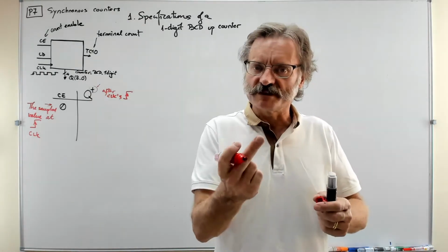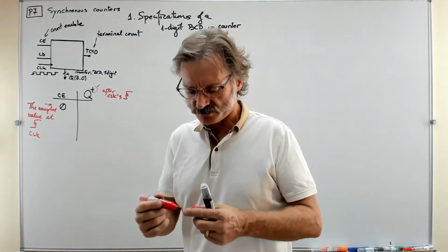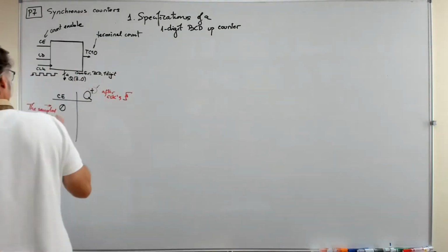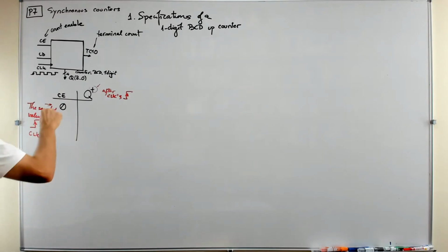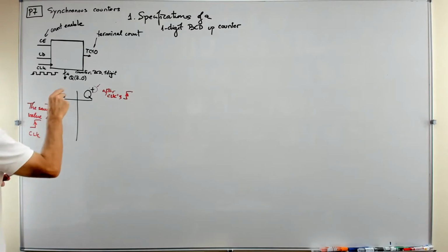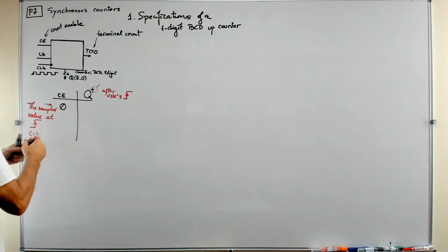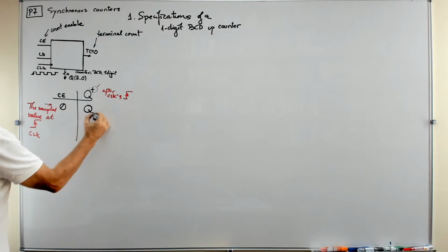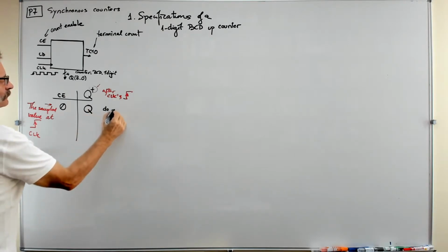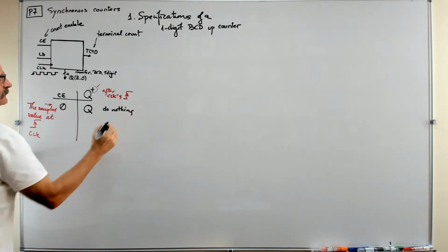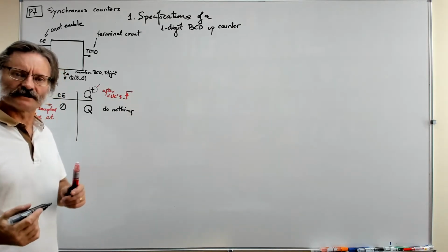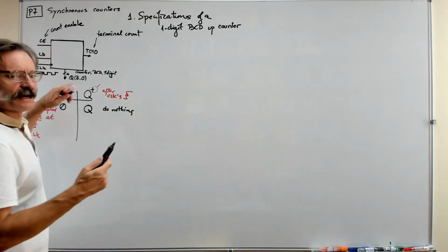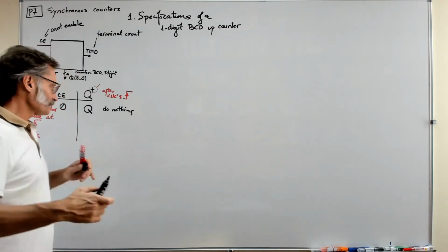Even the 1-bit flip-flops were invented like this, as asynchronous devices that have this mechanism related to the clock rising edges. This time, this machine, you see, it's like this. If count enable happens to be 0, the Q is kept the same, okay? Do nothing is the idea, or disable counting, you know? Or keep the same value. If the counter is generating now a 2, so after the rising edge you will still have the 2.